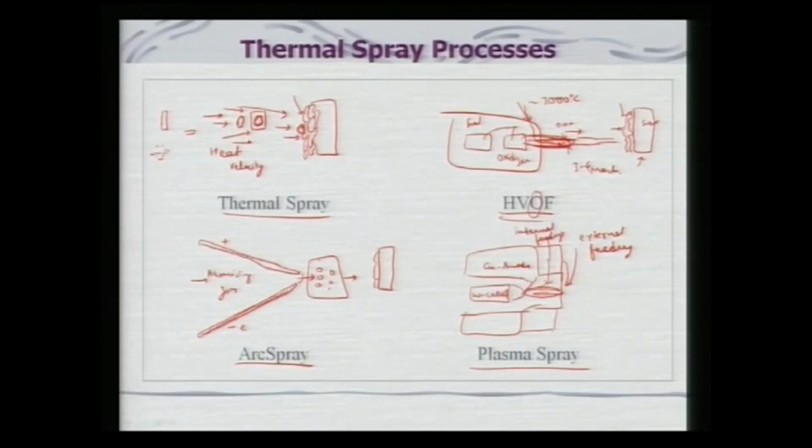That is very essential for high melting materials, such as ceramics, because they require a prolonged stay in the plasma plume. So, if we add them right where the plasma is forming, they will stay in the plasma plume for an elongated time. Certain ceramics such as aluminum oxide and yttria-stabilized zirconia need to be fed right where the plasma is forming.